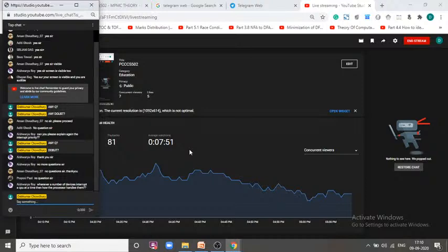One question came: whenever a number of devices interrupt a CPU at the same time, how does the processor handle them? Whenever different interrupts are requested to the microprocessor, it tries to find out the priority of each interrupt. Suppose INT1 and INT2 both occurred at the same time. We need to find out what the priority of the interrupt is. The priority of the interrupt is stored in the priority table, which is kept with the microprocessor.